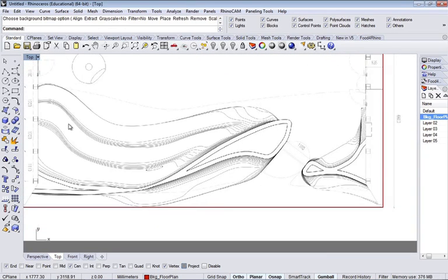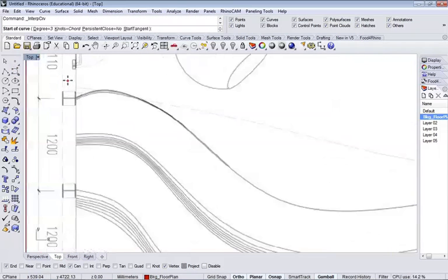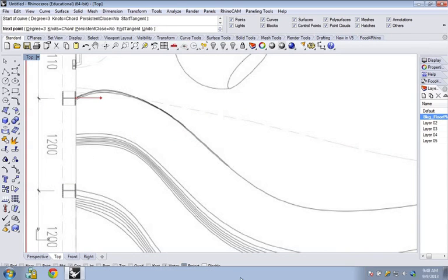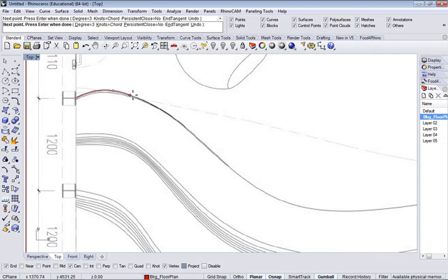We can start to develop a series of curves. And what I would use when you do this is actually not this control curve, but these interpolated points. The reason I would do that is because each of the points on an interpolated curve is right on the line where you're clicking. So if I click here, let me turn off ortho, and I click here, and I click here, you can see that it's already starting to align very nicely.